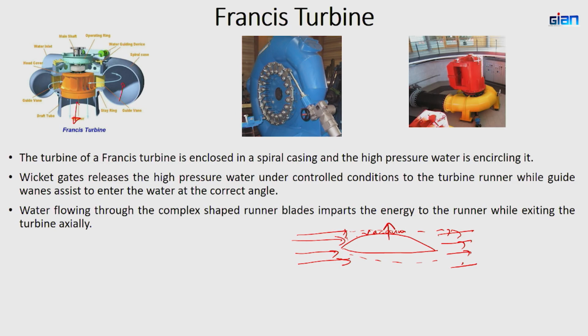Here we can see the hydraulic control of the wicket gates. You can see this will be rotating these brackets which are connected to the wicket gates inside. So, when you want to open and close, this will be going up and down, right, and the hydraulic pressure will come as per the signals coming from the water level controller or from the control system in the power plant, right.